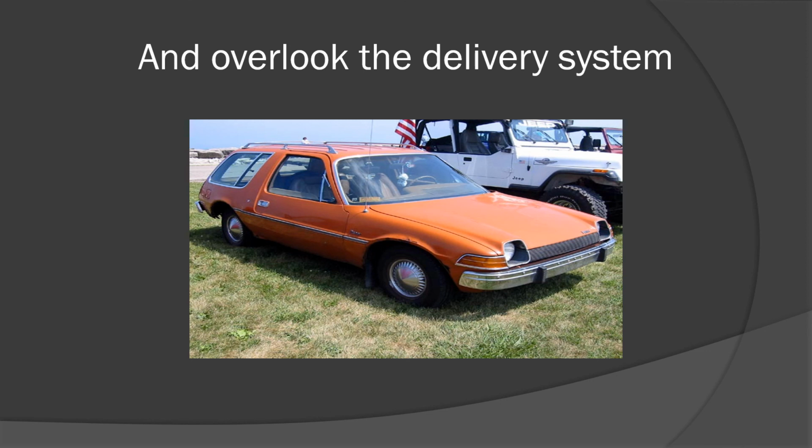If we put a very high end, very efficient piece of equipment on a poor delivery system, we will end up with a poor system. The greatest, most technologically advanced piece of equipment in the world cannot overcome a poor air distribution system.